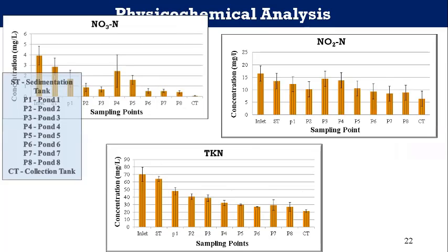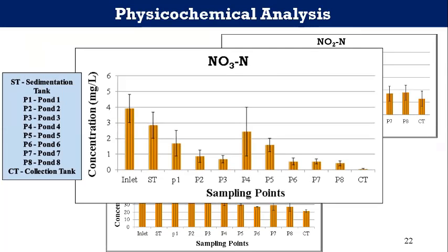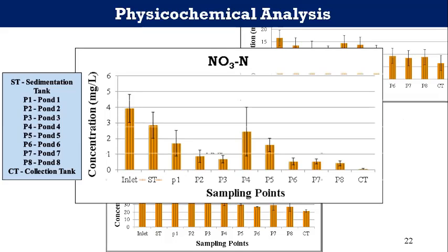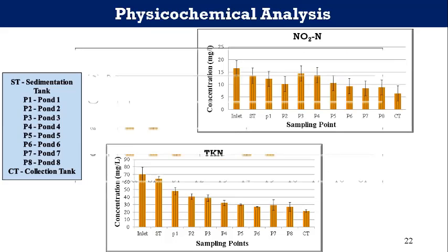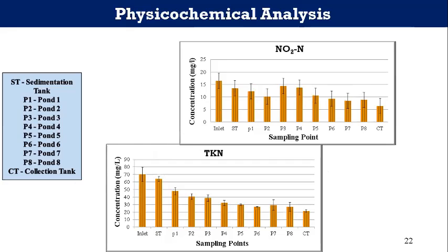Nitrates contribute to the discharge of sewage, industrial waste, runoff fertilizer, and decay of vegetable and animal matter from agricultural land. Nitrate production in the integrated constructed wetland is enhanced by facultative microbes present in it. Low nitrate nitrogen concentration was recorded at the wetland outlet. It may be due to denitrification, where nitrate is converted into diatomic molecular nitrogen, deposition of nitrate in sediments at the wetland bottom, and uptake by plants. Nitrate varies constantly and shows no significant trend.